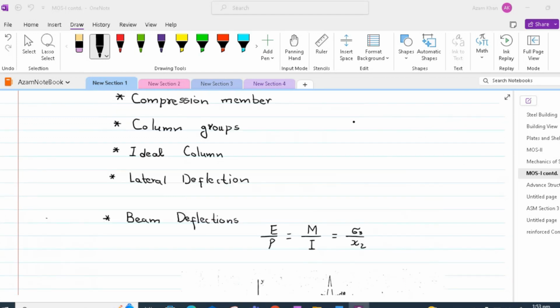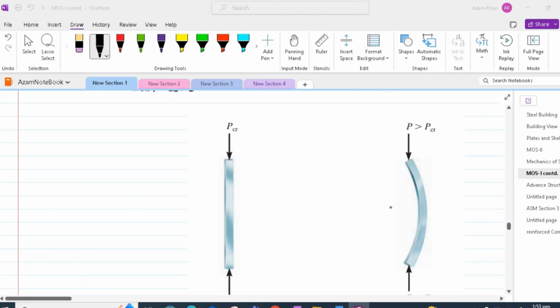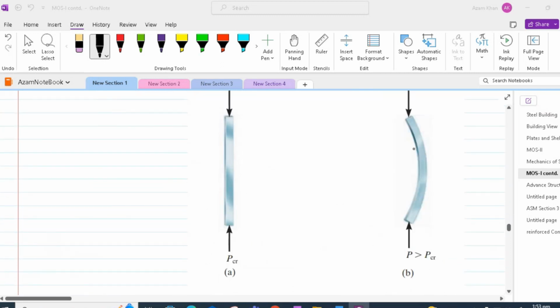this second figure shows buckling of a column. Therefore, the buckling failure differs from the compression failure. In the buckling failure, we have the column undergoing lateral deflection. Thus, there is a cutoff length above which the column will buckle. Below that cutoff length, the column would fail by crushing. Although there is no sharp line of demarcation between short compression members and columns, a compression member is generally considered to be a column when its unsupported length is more than 10 times its least lateral dimension.